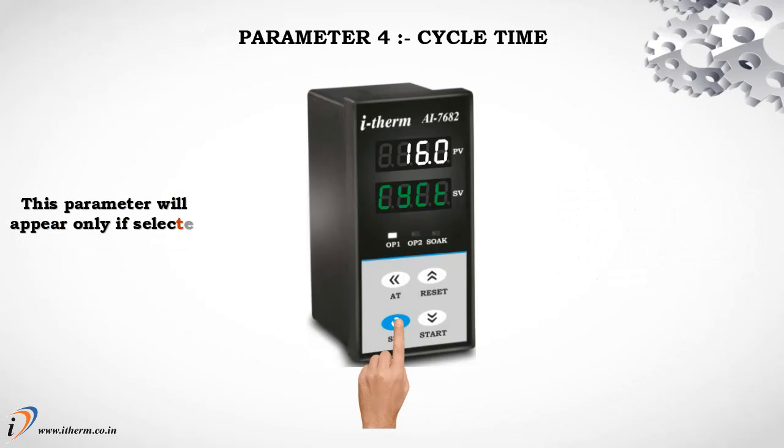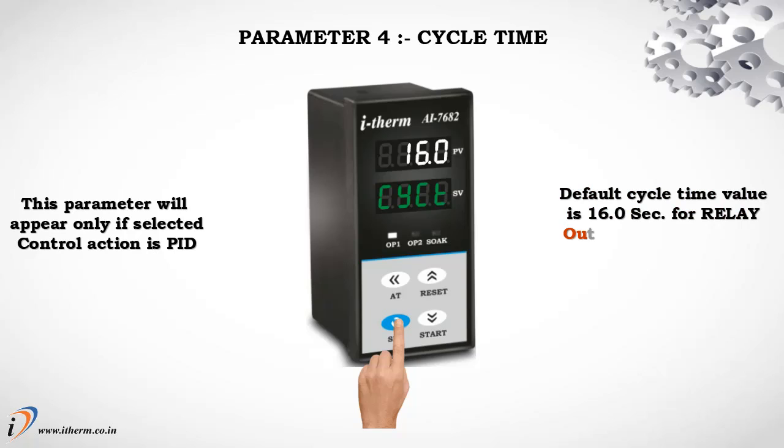Parameter 4, Cycle Time. This parameter will appear only if selected control action is PID. Default cycle time value is 16.0 second for relay output and 1.0 second for SSR output.